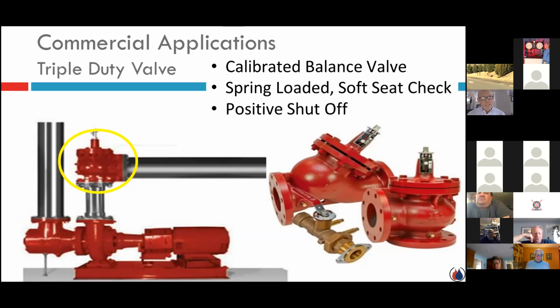And so on the day of commissioning, when the pump was actually turned on, you want to find out exactly what it's doing, and you realize that it's over pumping because the pressure drop in the system isn't as great as perhaps we thought when we spec'd it. One of the techniques was to take this balance feature and balance it down, back the pump down on its curve so that it doesn't overload the motor, because it's capable of pumping more. The system is allowing the pump to really swing way out on its curve, is the expression, and it's moving too many GPM, wasting energy, and it could potentially cause cavitation and overload that motor.